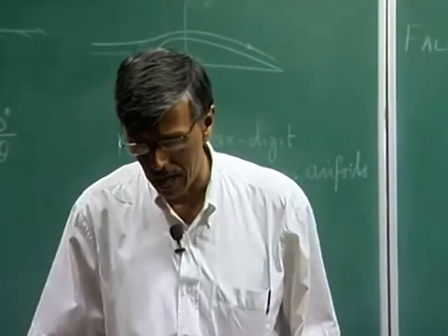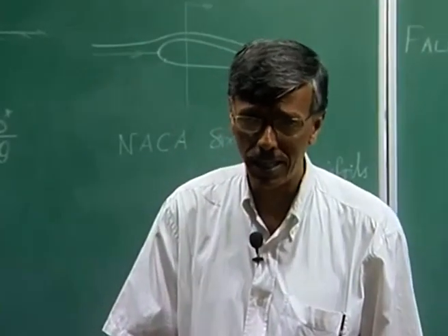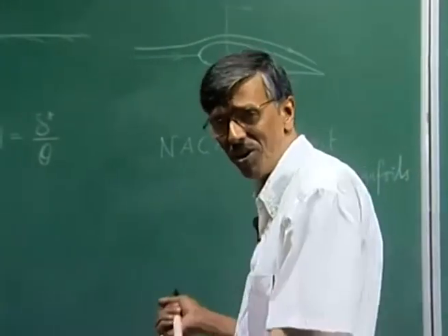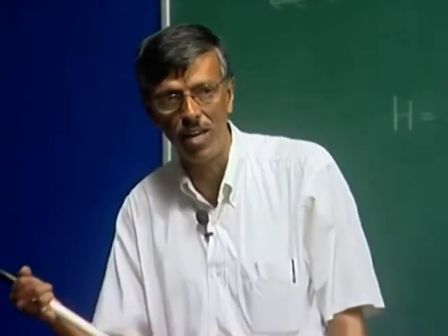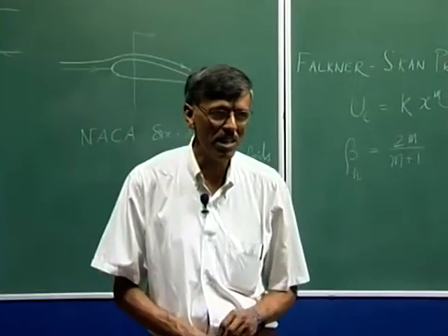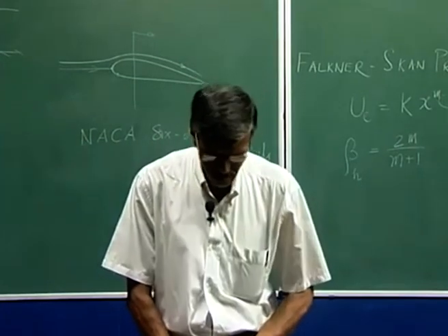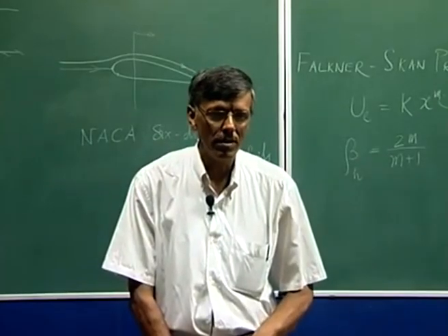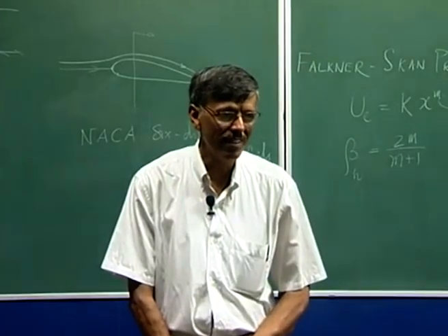In this respect also, I would like to sound a word of caution. Despite what all the experimentalists trade among themselves, saying, oh, I have a tunnel of turbulent intensity of this value and that value, please be aware, they may not know what they are talking about, because the turbulent intensity is also a function of the oncoming flow velocity, right.